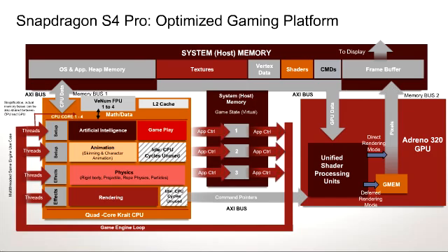Okay, this is a flow diagram that shows the data flow for a game or a graphics application on an overall Snapdragon system on chip. As you can see on the left bottom side, there are multiple CPU cores. In this particular case, I've represented 4 cores here, and this is only a representation, so I've simplified it a bit for you guys. The CPU cores are processing individual functions from the game engine as they use multiple threads. And you can see some of the idle cycles that I've identified by highlighted checker boxes, specifically on the second core and the fourth core.